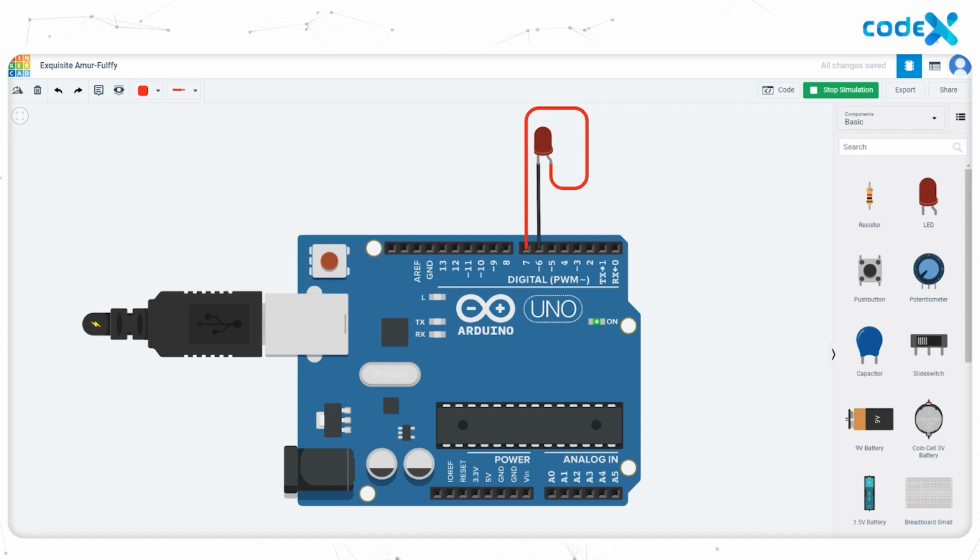This is because pin 6, where we connected the cathode of the LED, is getting high, and pin 7, where we connected the anode of the LED, is getting low state. That is, the LED's positive is set to low and the negative is set to high, which turns off the LED. Now you know how to turn the LED back on, right?